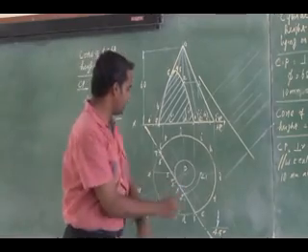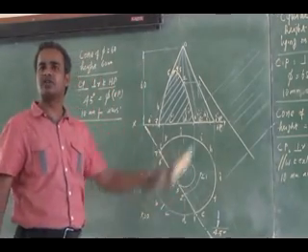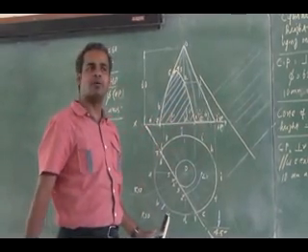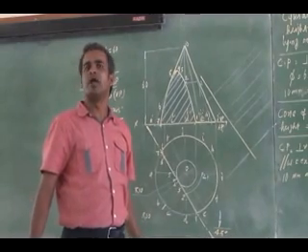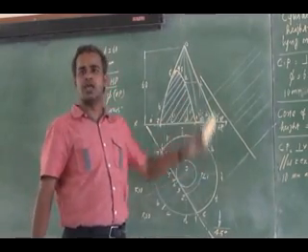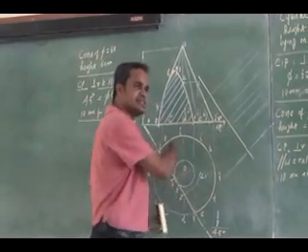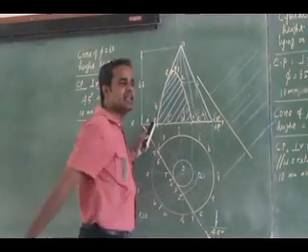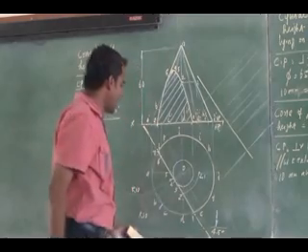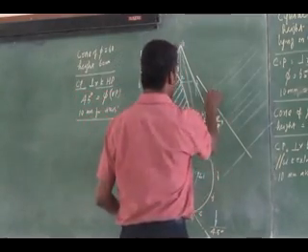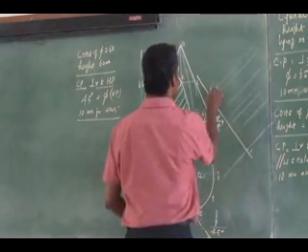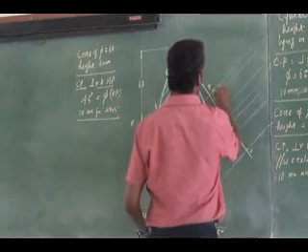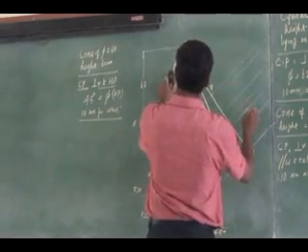The section is parallel to the axis, so which is your true shape? Will it be a parabola or hyperbola? Hyperbola. You will get a hyperbola. It cuts parallel to the axis and the incline. You transfer these sectional points to the true shape. So this is my cutting point 1 and 7. If I project these points, I will have a cutting point maximum of this.